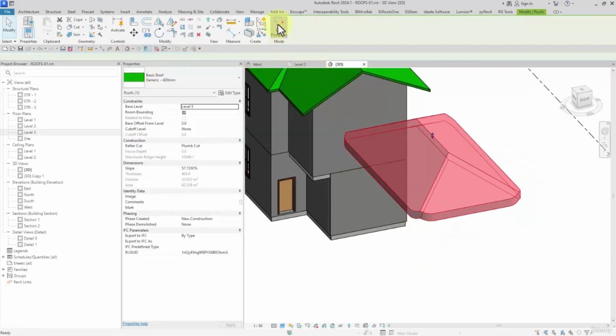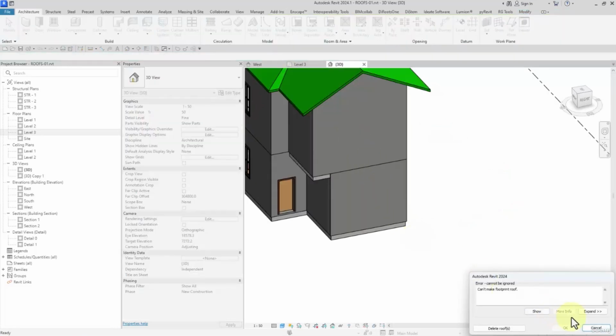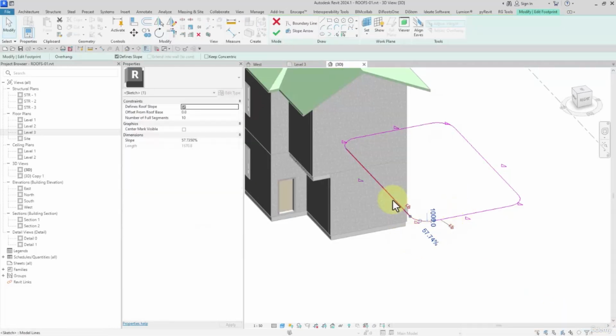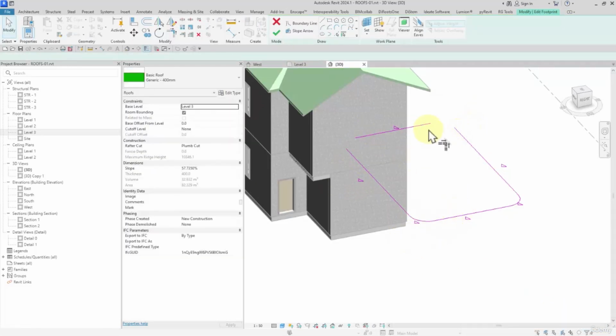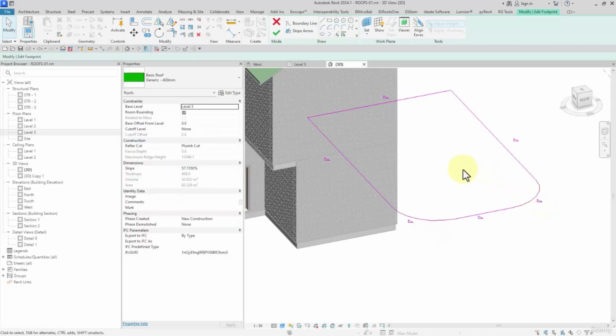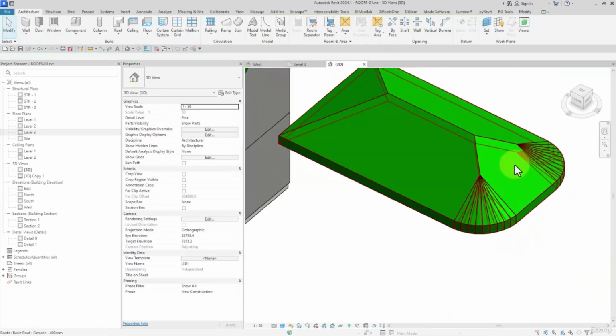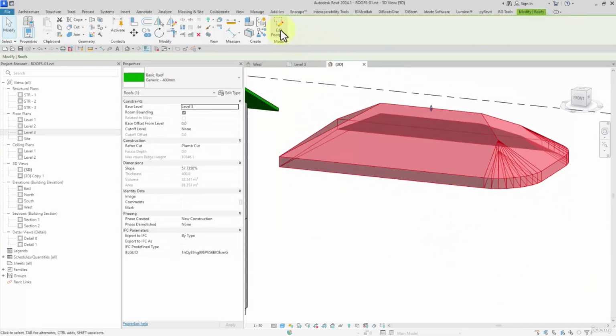Watch this. Again I edit it, selecting them, define a slope, 10 parts. We have to increase the size of the arcs. Let me trim them. I want to increase the radius, 2000 and 2000. Okay, watch this. It is divided into 10 parts.